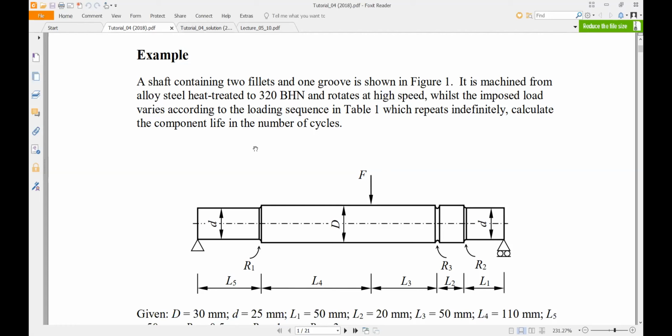So for plotting the Sn curve to determine the life of the component, what should we use, is it the least Sn value? Yeah, least. We need to consider the least strength value, I mean the curve which gives the least endurance limit. Okay, that's good.